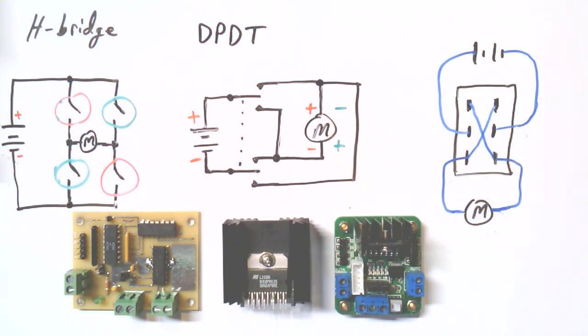If the bit's high or the bit's low, you'll have the H-bridge switched one way or the other, for example. You can use this not just to control direction of a motor, but you also build in maybe an enable, where all of the contacts switch off, the transistors are off.